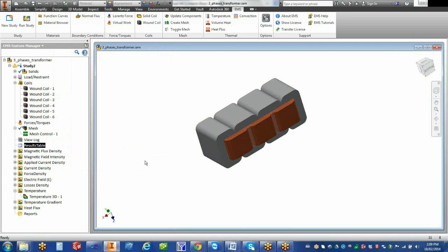And the unknown the software actually solves for is really the magnetic field. So all of the results table data is really post-processing. We solve Maxwell's equations directly and obtain the magnetic field at each node in the finite element mesh. Okay, and then from that we derive everything, whether it is the energy, inductance, capacitance, force, torque, flux linkage, impedance, voltage, current. All of them are actually derived from the